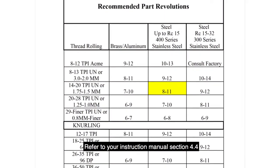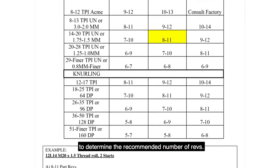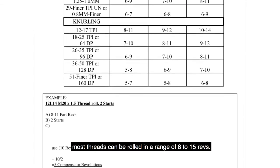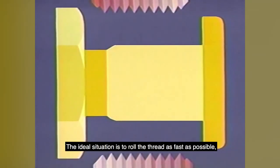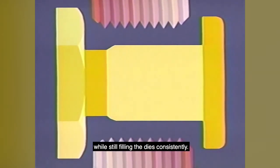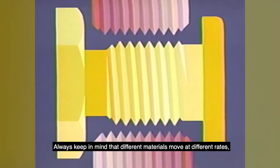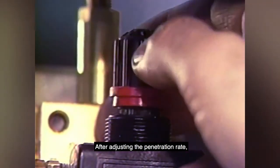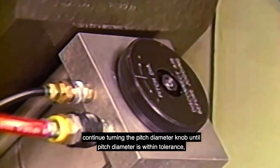Refer to your instruction manual, section 4.4, to determine the recommended number of revs. Depending upon the material and thread that you are rolling, most threads can be rolled in a range of 8 to 15 revs. The ideal situation is to roll the thread as fast as possible while still filling the dies consistently. Always keep in mind that different materials move at different rates, so several variations will be found in this area. After adjusting the penetration rate, continue turning the pitch diameter knob until pitch diameter is within tolerance and/or the go and no-go gauges fit properly.